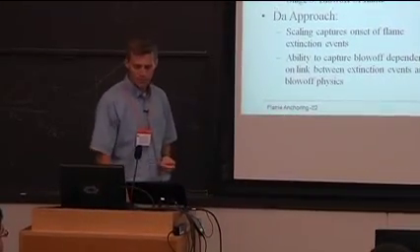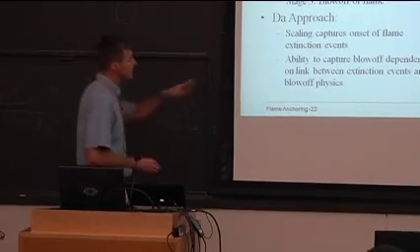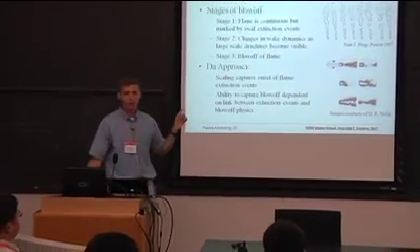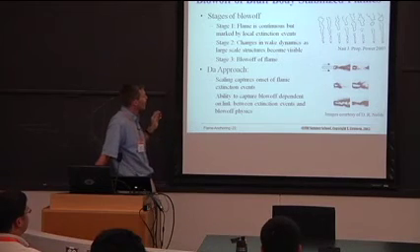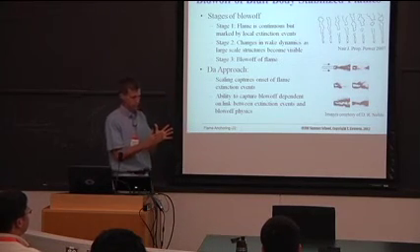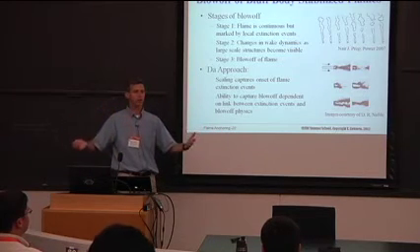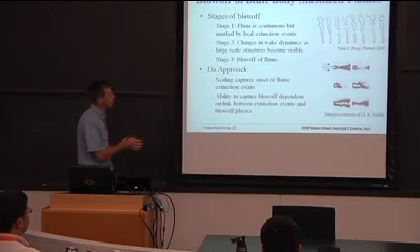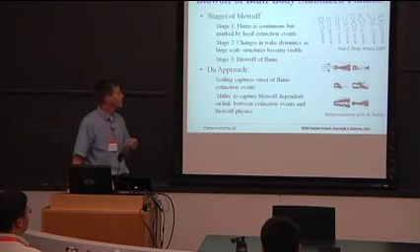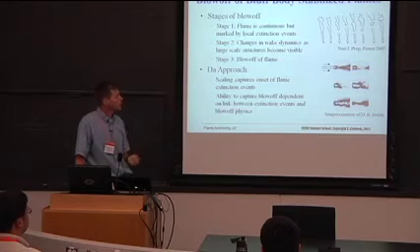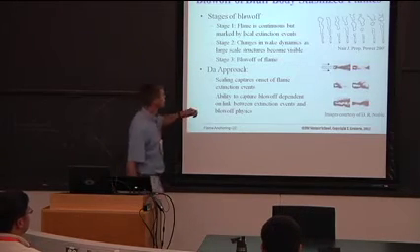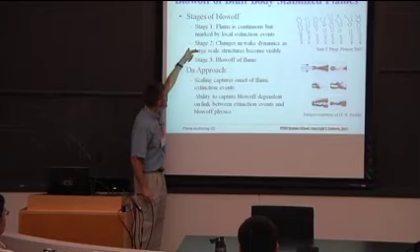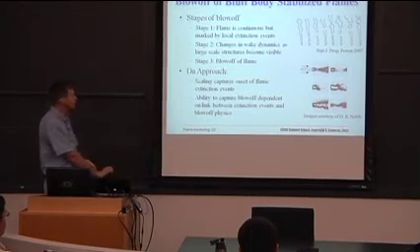But what happens is something that's not extremely well understood: this stage 2 of blow-off. Okay, don't take me wrong. This flame will eventually blow off. But blow-off is preceded by this whole range of fuel-air ratios where there's just very crazy combustion, where the flame's got lots of holes and all kinds of crazy stuff's happening. And what usually seems to happen is that as you start to approach blow-off, you get some wholesale changes in the fluid mechanics, the hydrodynamic stability of the flow. And all of a sudden, for some reason we don't really understand, as you move from stage 2, bang, the flame blows off. But this relationship between stage 2 and stage 3 is still a very active subject of research.